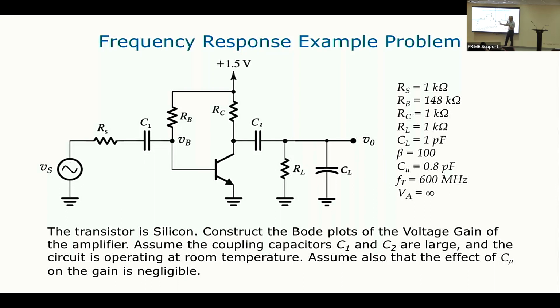And this would be the input resistance and the input capacitance. Now, why do you need this? You need this because there's a DC component that exists at the output here, and you have to get rid of that DC component. So the function of C2 is the same as the function of C1. That is to get rid of any DC component that is present in your signal. At the same time, this one will isolate your input with respect to the DC biases. Because this acts as an open circuit for DC, whatever bias currents you have here will not go back toward the input signal. Same thing with C2.